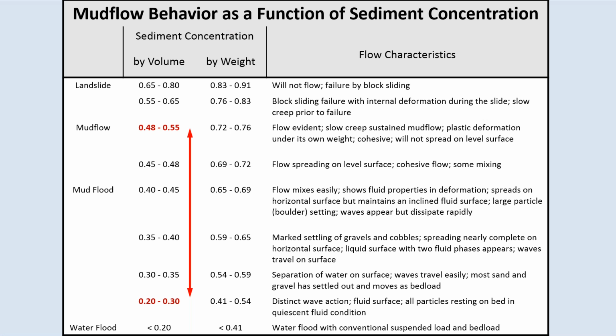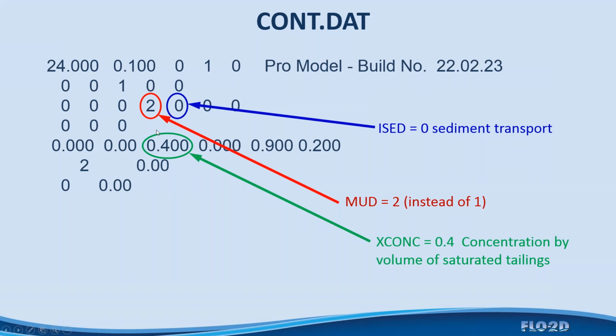So everything that I'm talking about here in terms of this two-phase flow and all of these rules that I've imposed have to do with this graph, which I created in a laboratory analysis of mud debris flows by taking a number of different samples and putting them into almost like an aquarium, and mixing them and sloshing them around and so forth, knowing the concentrations by volumes. And so this is how I arrive at 20 to 30% concentration by volumes when I talk about mixing, and how I arrive at 56% concentration for mud flows that cease flowing and become landslides.